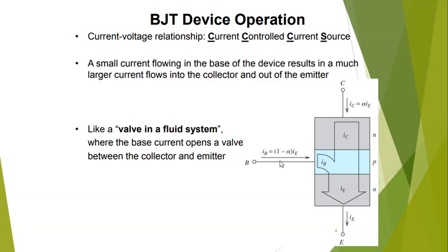But how does this system order the compressor to turn on and off? It measures the temperature using a sensor, and there is a basic logic unit, a processor, a controller that compares the temperature from the sensor with the set temperature that you set in the system.